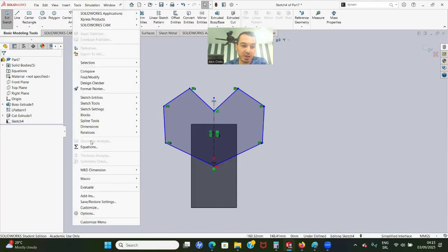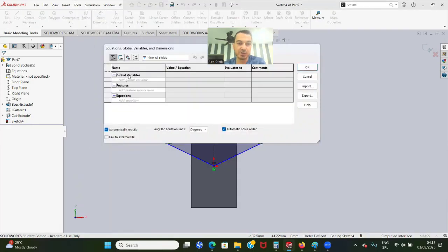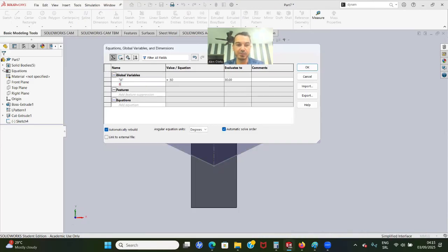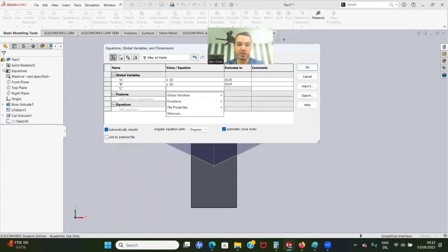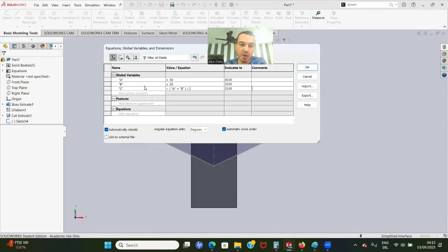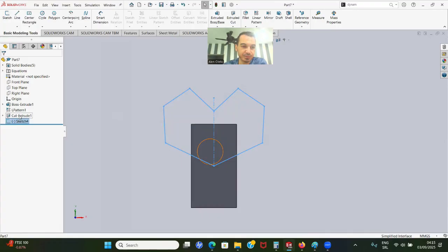So if you go here to the tools, here you're going to find equations, right? So for example, you can define the first variable, or global variables. Let's say A is 30. Then we have B, that's 20. And then we have C, and we can say, okay, C is A plus B. We can put that in brackets. And we can say this is now divided by 2. And this is our equation now. And these are all global variables. Let's click OK.